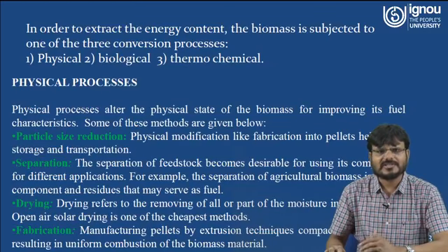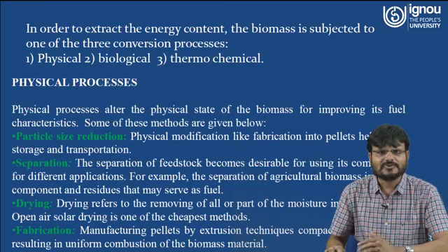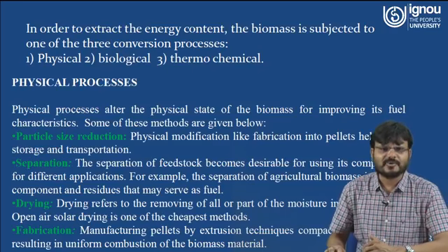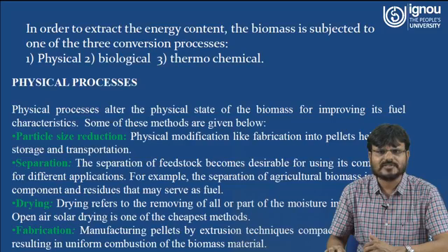In order to extract the energy content, the biomass is subjected to one of the three conversion processes that can be used to extract the energy content. First is a physical conversion process, second is a biological conversion process, and third is a thermochemical process. Now we have to understand what happens in the physical process. The physical process alters the physical state of biomass for improving its fuel characteristics, and some of these methods are